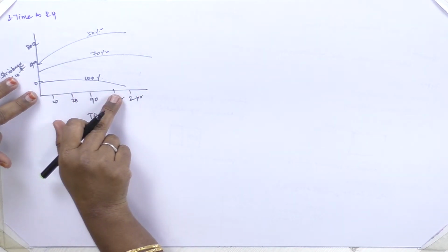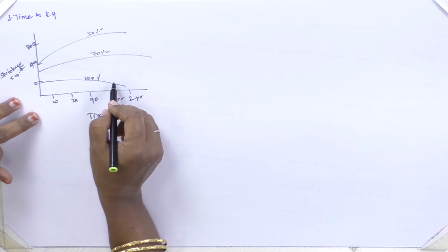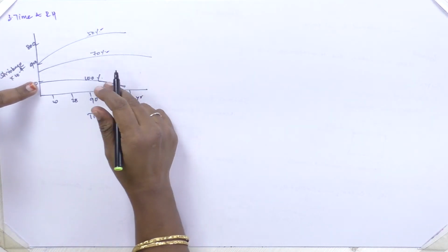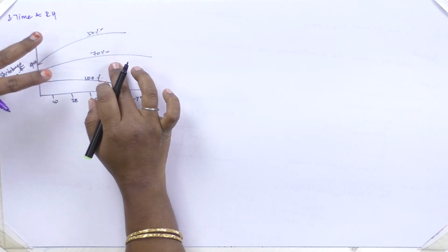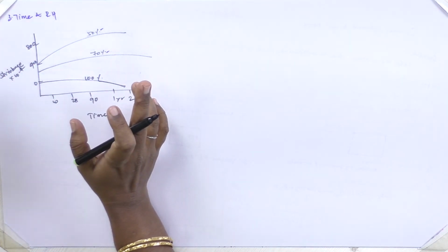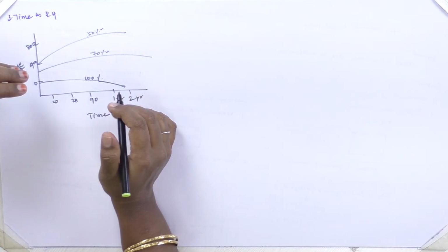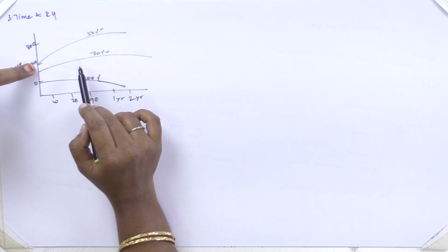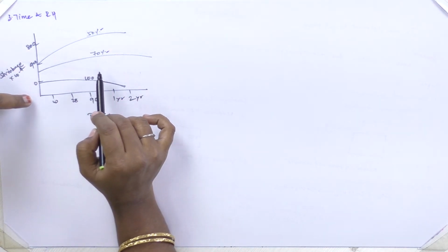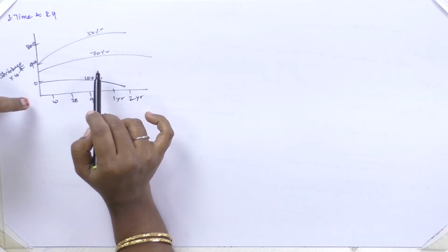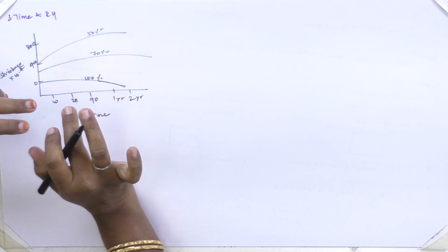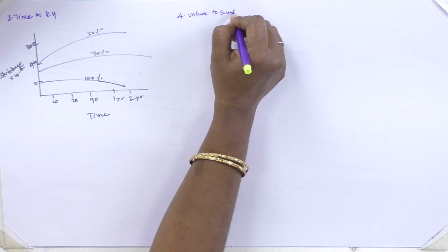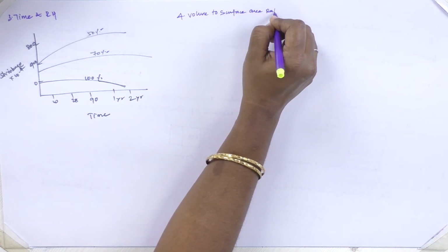If it is a fully saturated specimen, then there arises a decrease in shrinkage, that is, swelling occurs, whereas if it is 50 or 70%, then there will be movement of water from gel pores to capillary pores, and because of that there exhibits a little shrinkage compared to that of the specimen having 100% relative humidity. And next is volume to surface area ratio.